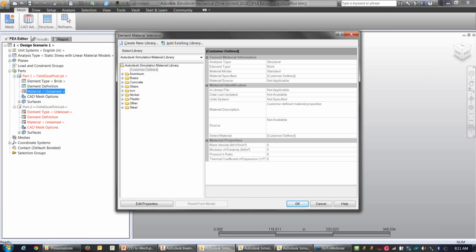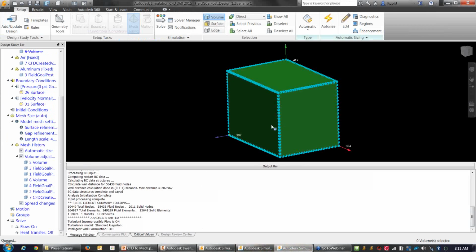Okay. No, there's no need for any boundary conditions on the poles themselves. There's no constraints, and everything's rigid in here. Just the volume here is considered fluid. So we only have our flow in and our flow out. The program will recognize the solid parts as solids and creates the boundary condition on them. The mesher, using automatic mesh sizing, automatically creates the boundary layer on all solid parts and along any external fluid volumes. Does that answer the question there?